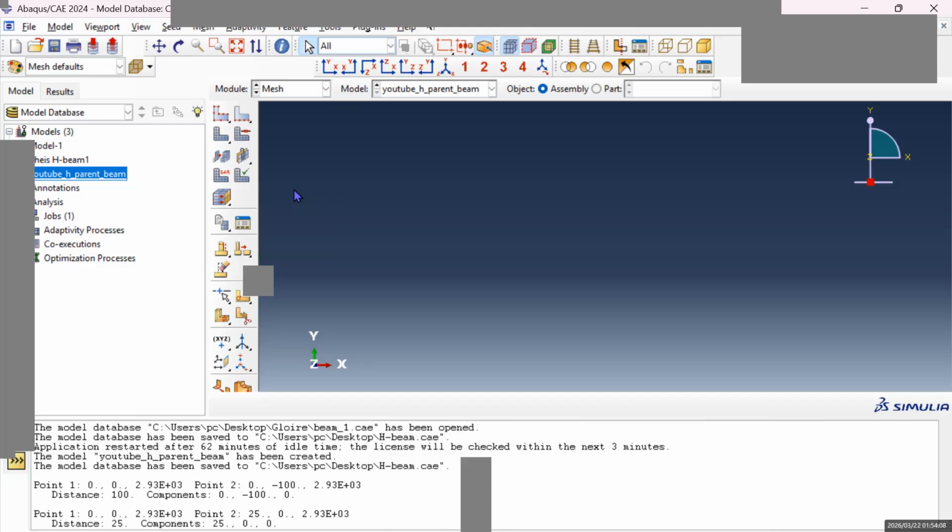In our minds we know it's a steel beam, and we can use hand calculation to calculate the forces, but without meshing your model, the computer won't be able to calculate all of the forces on it, like boundary steps, like forces on it. So when you mesh it, you divide the beam into small pieces, and then you allow the computer to calculate according to those pieces. This is how it works.